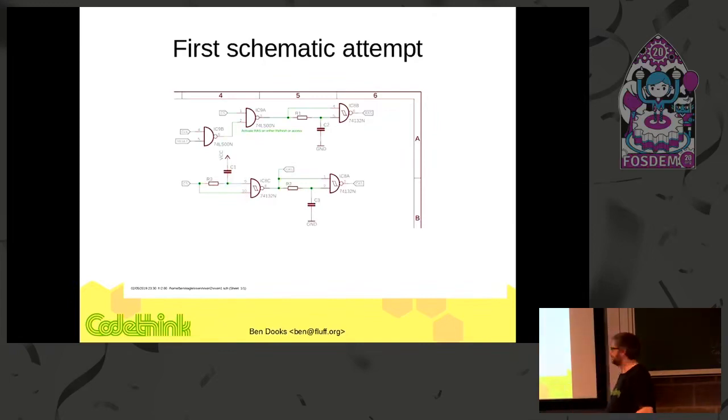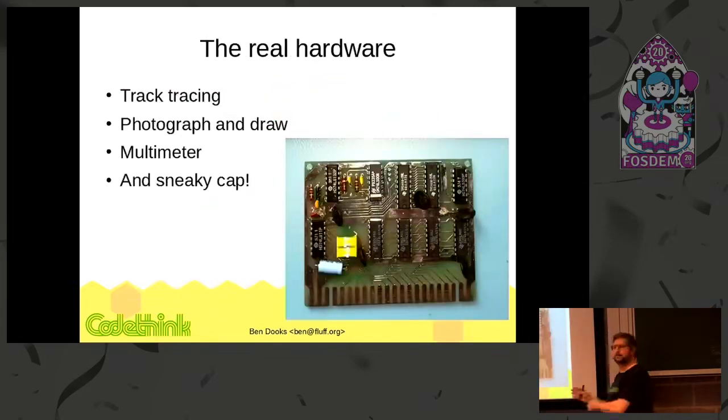I could just leave this alone. No, I go on eBay. So the first start of this madness is that I actually buy one. I find one on eBay. I spend about 30 euros, take it out of its cartridge, and I'll show you later, I've got it here. And I take a photo. This is the first stage of a full reverse engineering of this sort of thing. I've got a photo of this, and a photo of the underside of the board. Unfortunately, you can't really see on this projector, but you've got two DRAM chips, the counter, the 2-to-1 muxes for the address, and some logic.